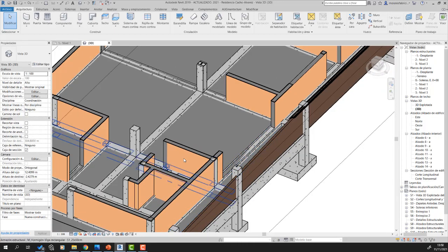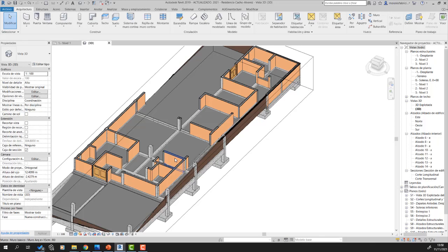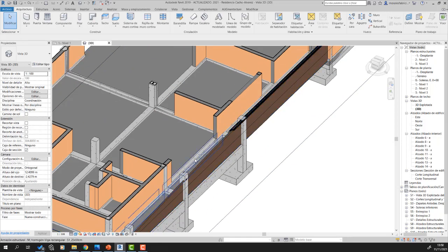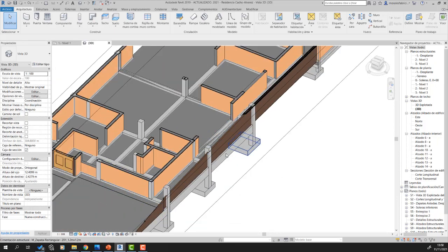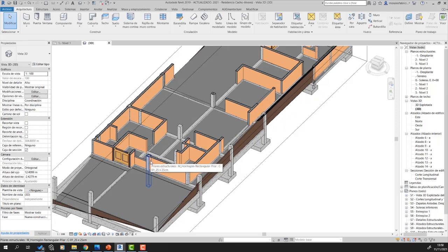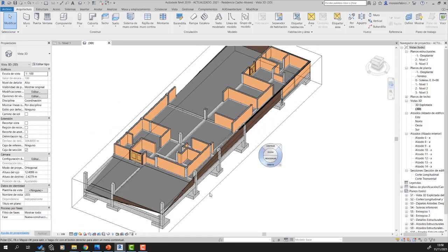So usually the inside spaces, for example the kitchen or the living room or the reception and the laundry area and so on, need to be a little bit higher than the rest of the levels of the house. And that height is usually 10 centimeters here in Honduras.